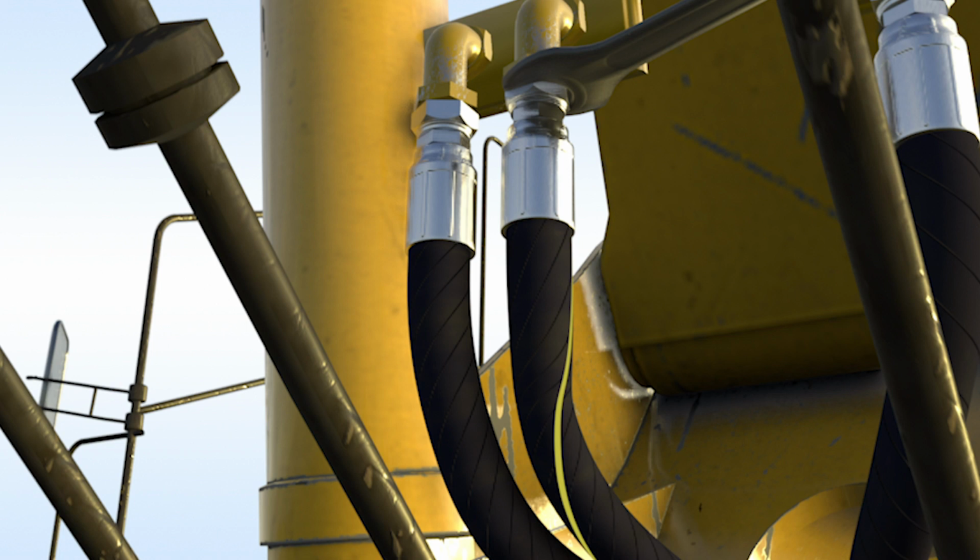Looking at the hose on screen, what is the negative effect on the hose assembly in this scene? The life expectancy of a high pressure hose is reduced by as much as 70% with a 5-degree twist, and a 7-degree twist can result in a 90% reduction in service life. How could the twist have occurred? And how could we prevent this from occurring?